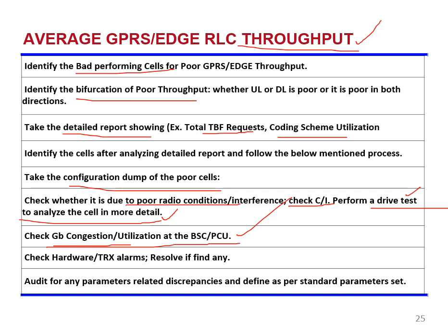That link also should be verified, the Gb link. And also you have to verify whether any hardware issues are there. So you all noted between BSC and SGSN, the GPRS Support Node, the interface is Gb. Between BSS and SGSN, the interface is the Gb interface.